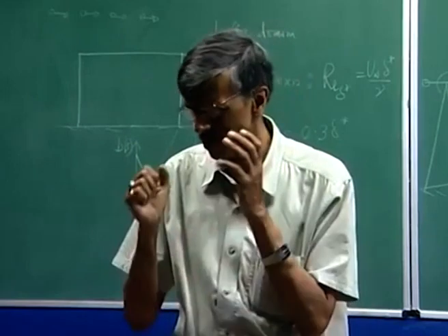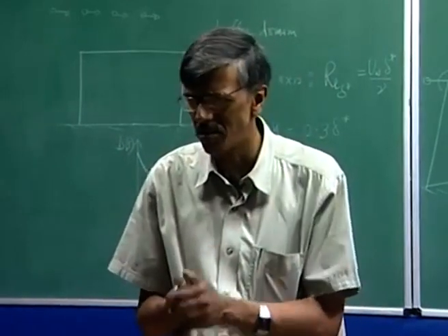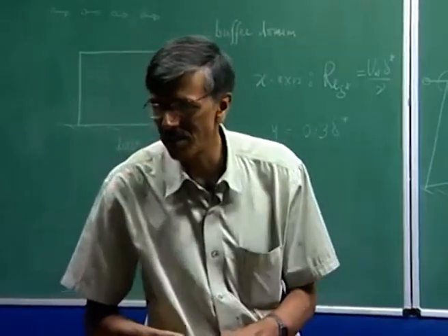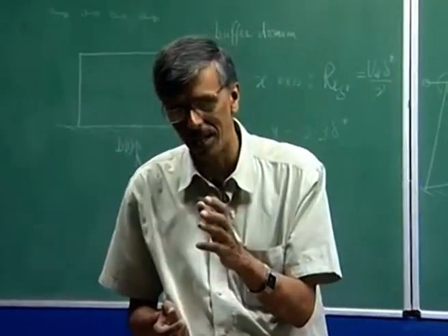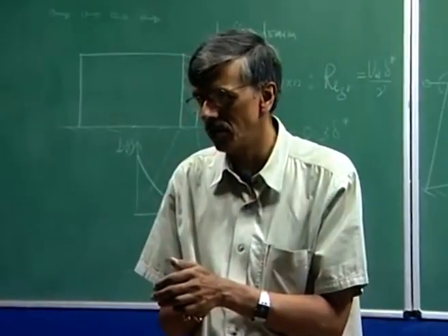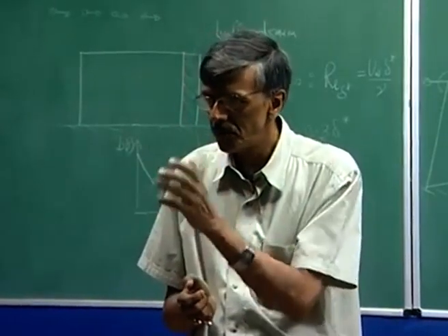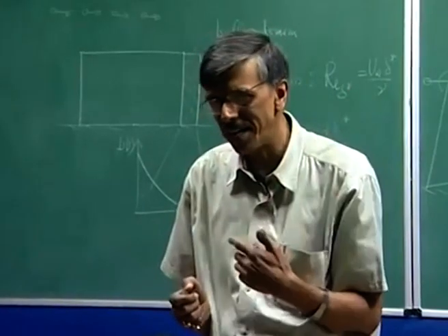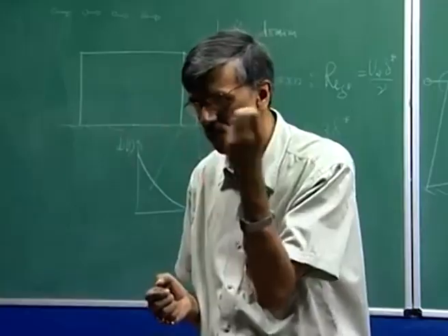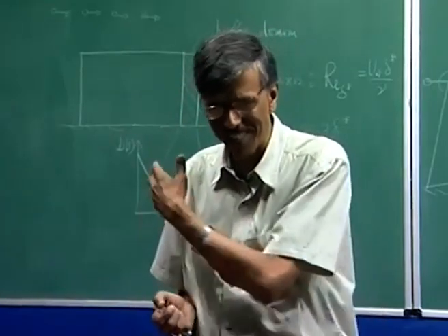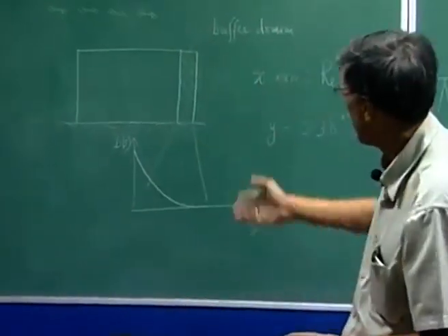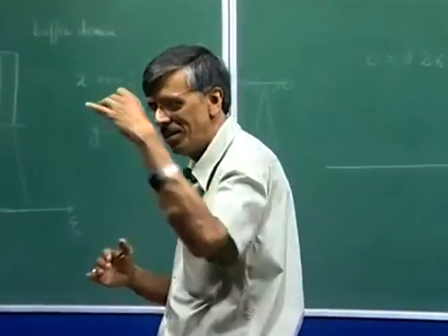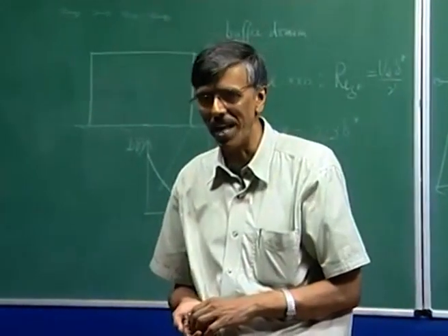Because that is too contaminated with disturbances due to the combustion process in the combustion chamber itself. But if you look at the compressor part and you look at the stator behind a rotor, then the rotor is rotating. So, it is going to give out periodic vortices, exactly the same kind of thing. So, instead of a flat plate, you should be talking about a compressor blade and vortices going there.